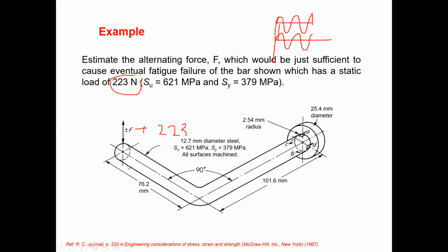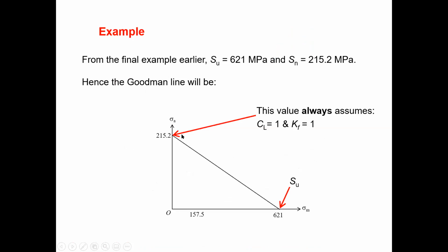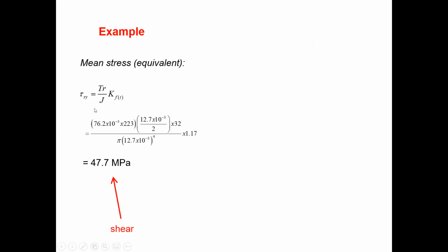So this governs the torsional load, and this distance governs the bending. So due to this load, bending and torsion again happen. We already calculated the equation for the alternating value, and now we need to find the constant value stresses. You can find it this way.